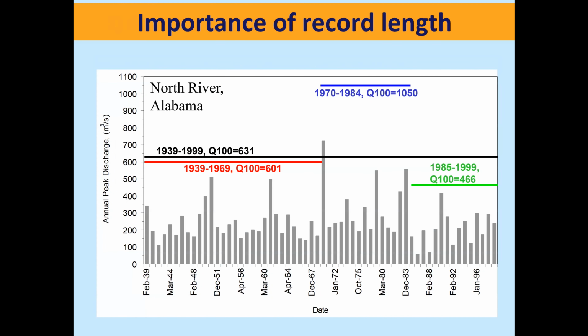One point that's pretty important to make on stream gauges and their period of record is that not only do we have a limited number of stream gauges in Alaska, but we also have ones that maybe don't have as long a record as elsewhere. And this chart shows that if you were to do that Log-Pearson 3 analysis of gauge peak flow records over different periods of time within a particular stream gauge's record, you could get some really different results for what a 100-year flood might be.